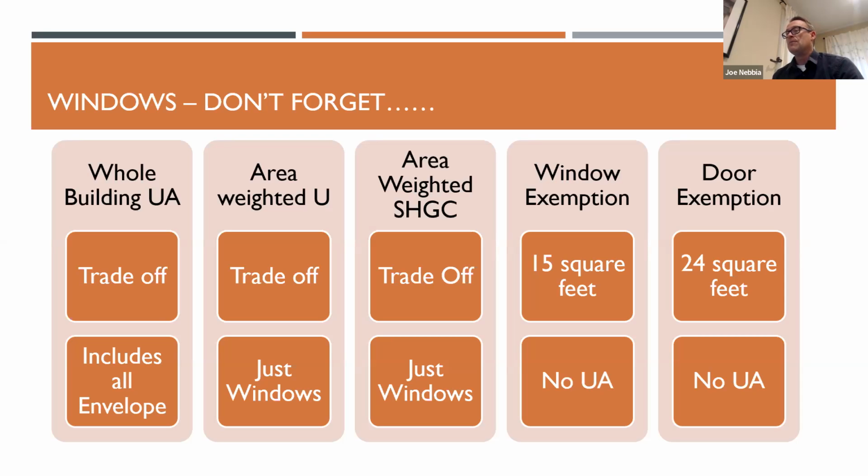So check chapter 5 for those details on alterations and repairs. But if the local code official says we want you to put in a code compliant window, that's just what you have to do. But again, I do think a strict read of the code would be that you could remove the window during a renovation and put it back in its place without having to upgrade it according to code.